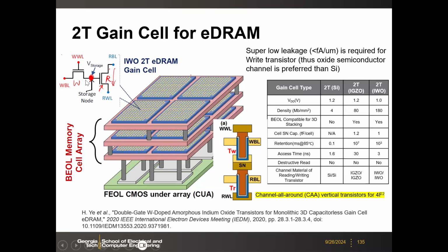Okay. So this is a DRAM because here the charge will leak, right? You have this off current through this read transistor, and then the charge will leak over time. So it's not permanent. So that's why this is a DRAM. You still need to refresh.